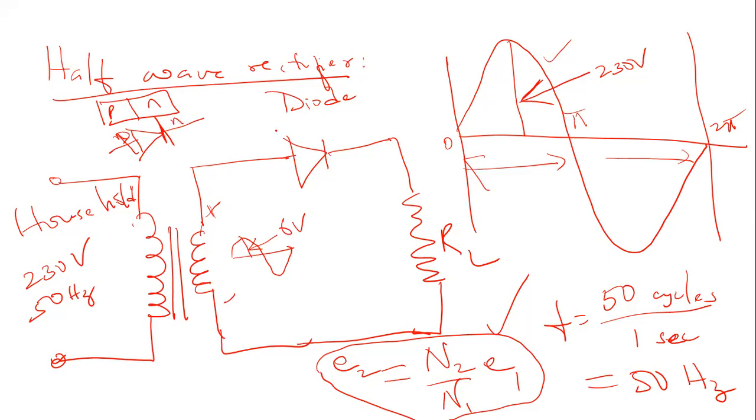So you have a PN junction diode like this. And if you connect the positive terminal to the P type and the negative terminal via the load resistance to the N type like this, it will forward bias your PN junction device. Okay, so if it forward biases the PN junction device, like I explained in the IV characteristic curve, under forward bias this PN junction will allow flow of current.